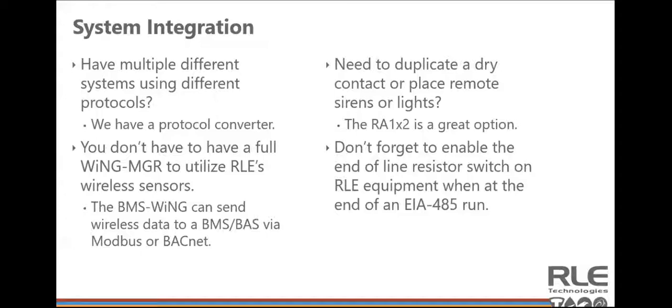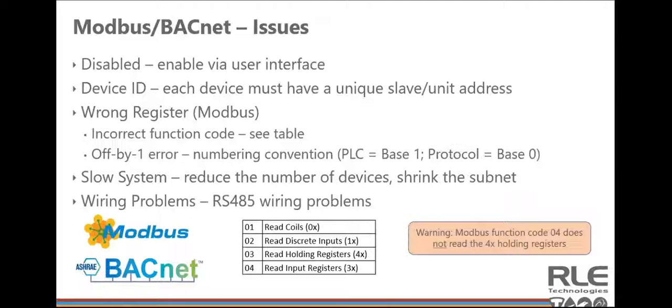And one of the neat pieces of equipment is a protocol converter we have. Great for legacy devices where you've got legacy equipment, you've got a new building management system, or vice versa, and you need a device that can aggregate a whole bunch of points from, say, a Modbus or some other type of 485 communication and transfer that over via SNMP. So keep that in mind. And again, then turn it over to Brian for some more Modbus and BACnet specific troubleshooting.